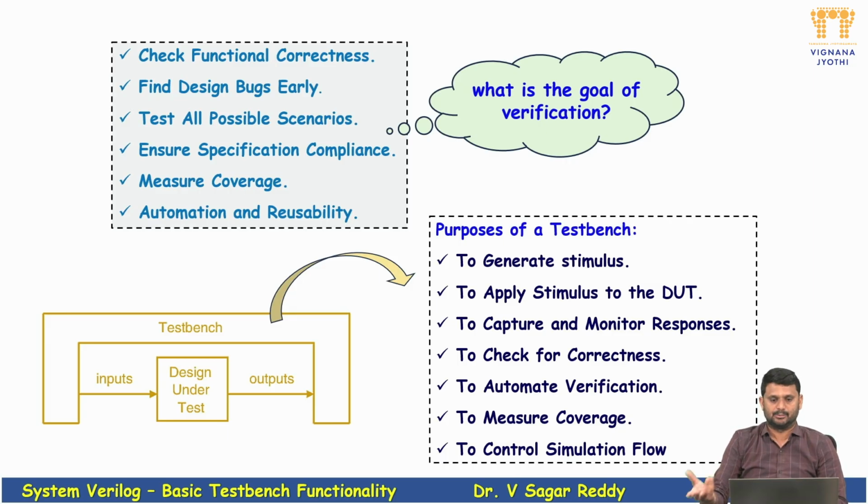Checkers and scoreboards detect functional errors automatically. Next, to automate verification, reduce manual checking by automating the test process, which enables regression testing, running multiple tests automatically. To measure coverage, ensure all the features and corner cases of the design are tested, which helps verify the completeness of testing. And to control the simulation flow: start, restart, and stop the simulation, manage the test sequences, and randomize. Everything is done in the control of the simulation flow.